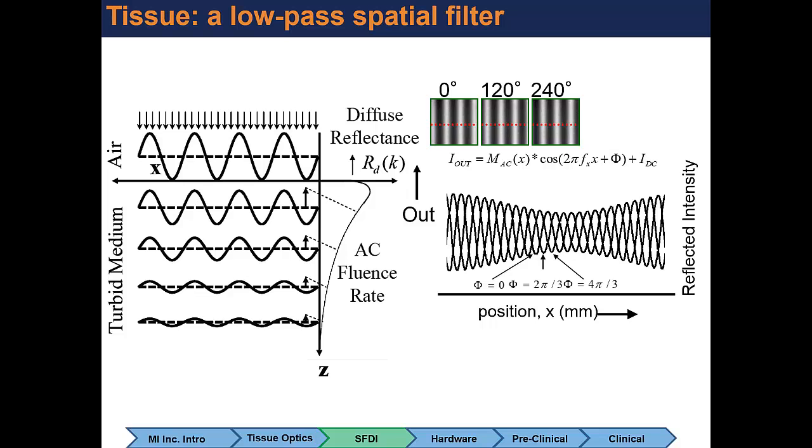You could do one phase projection and use other envelope detection methods. There's single sideband demodulation that requires a Hilbert transform, which basically takes a sine and transforms it into a cosine, and you combine them together to get an amplitude assessment. There are various ways to do demodulation. This is just a very simple one.